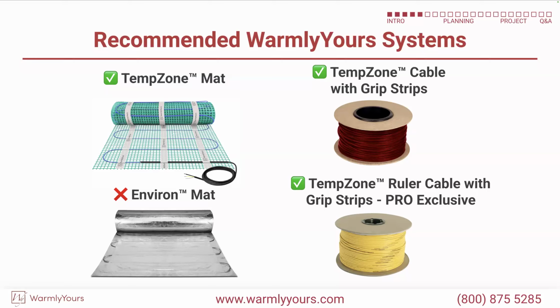Whenever you're installing these with the mat, always install it as much as you can wire side down and the mesh on top. Because you're going to be using hot glue to hold that mesh to the subfloor, so when you pour this self-leveling, it just doesn't float up into the top. So very, very important with that. If you're using cable strips and the cable, if you're doing long runs like across the room, 10 foot, 10 foot, 10 foot, you're going to want to take some masking tape every 2 to 3 feet and put the masking tape down along the floor to keep the cables from floating, because they will float, and they will come to the top.